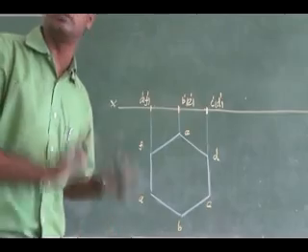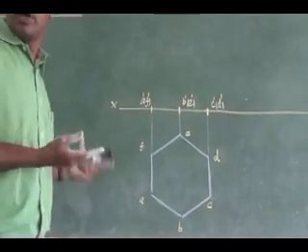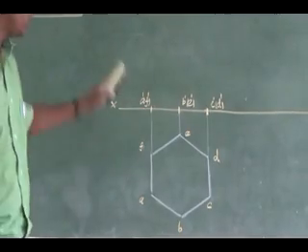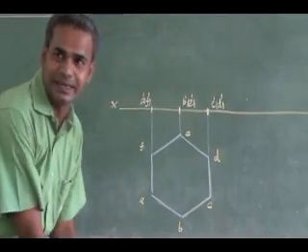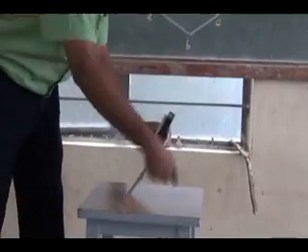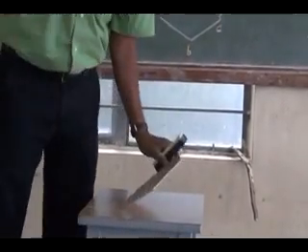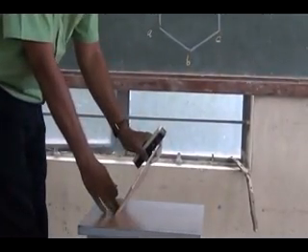I am assuming it is parallel, it is lying on the horizontal plane and it is perpendicular to the vertical plane. So I have drawn this. What is the problem actually? It is inclined. It is resting on the horizontal plane with the edge and the surface is inclined to 30 degrees. Right. So now this is going to be my final front view. Even though the surface is inclined, the front view will be a straight line like this. Okay. That front view I have got it.